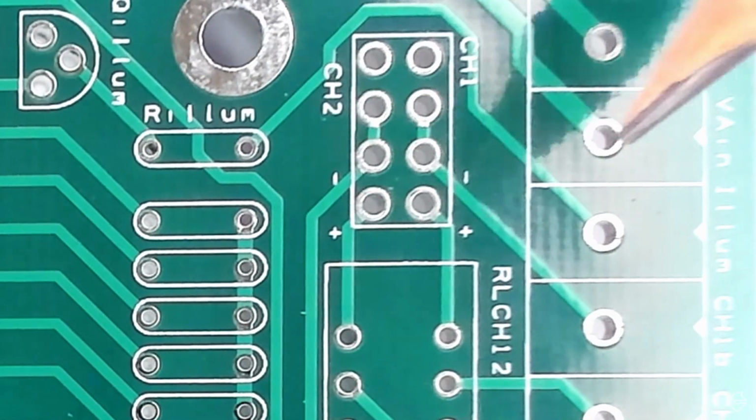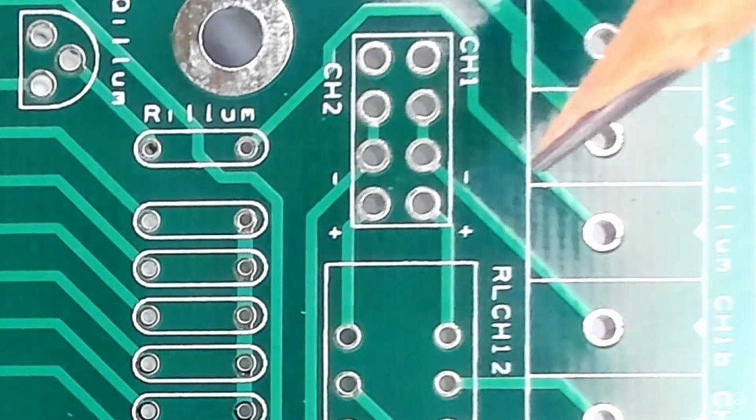We're going to solder these things in. You need to have a ring of sufficient thickness around every single hole. So we call it the annular ring. How thick does that annular ring need to be? Well, the standard gives some advice, and I'm sure if you Google it, how thick through-hole component annular rings need to be? One of the more common things that I've seen is doubling. So if your hole is 0.5, then the annular ring should be double that, or 1 millimeter. If your hole is 0.9, then it should be 1.8 millimeters.